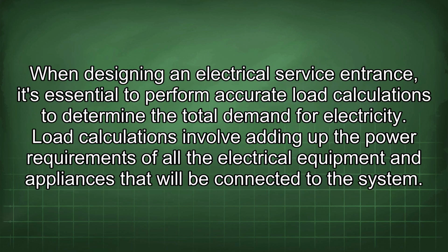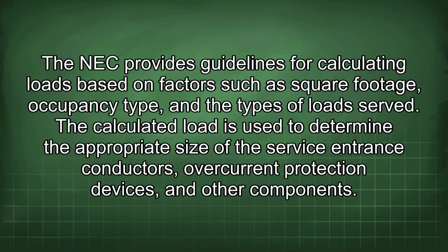When designing an electrical service entrance, it's essential to perform accurate load calculations to determine the total demand for electricity. Load calculations involve adding up the power requirements of all the electrical equipment and appliances that will be connected to the system. The NEC provides guidelines for calculating loads based on factors such as square footage, occupancy type, and the types of loads served. The calculated load is used to determine the appropriate size of the service entrance conductors, overcurrent protection devices, and other components.